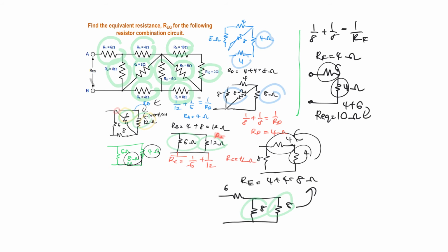But it depends also on the questions. For example, if I put like here without any junction, then R1, R2, and RT are going to be in series. Very good, because there is only one path. The current is going to flow in only one path, so it's series. But once you have a junction here, then you need to solve the question with the parallel method.